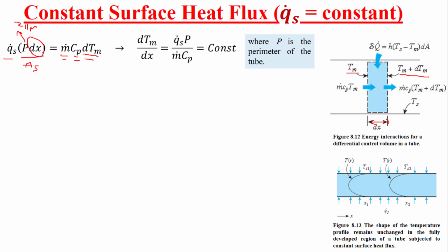So if I subtract the exit minus the inlet, T mean will cancel with T mean and we end up with delta T mean. Okay, so here is the equation. You subtract this value from this value. m dot Cv is a common factor, and T mean here cancels out with this one. So we end up with this equation for this portion.